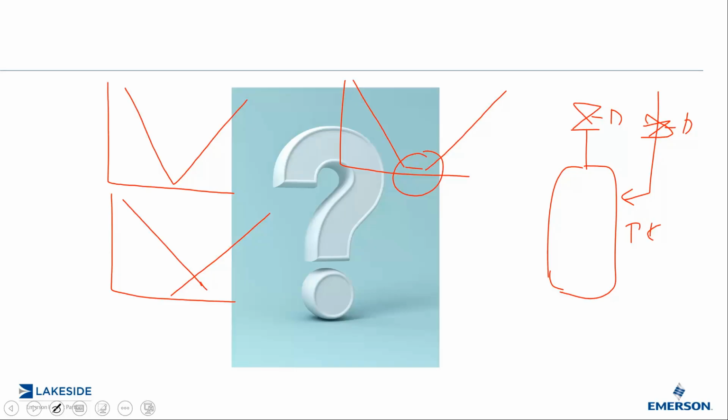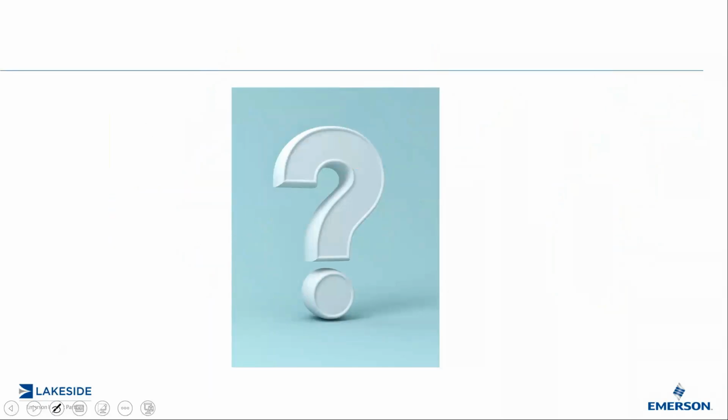But obviously, this would be done within the DCS, and you would have to consider which one of these would be better, because obviously here, if you're at 50% output, both these valves are closed. In this exact spot here, both valves are open, and again, that could be a waste of nitrogen. And so, depending on your control requirement, perhaps this one or this one may be better than using this scenario here. And again, a lot of scribbles there. Excellent question.